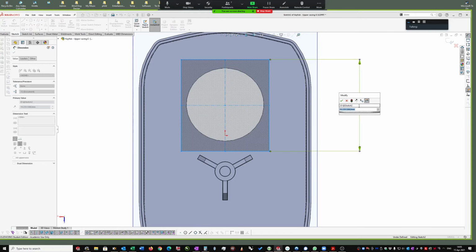Okay, so a quick calculation here. My button is 16 millimeters wide, and it's going to have a tolerance of plus or minus 0.1. So the largest it's going to be is 16.1, and I want a 0.1 millimeter gap between the button and the wall. So I need to add 16.1 plus 0.1 plus 0.1, that's 16.3. And then I need to divide my wall by 2.